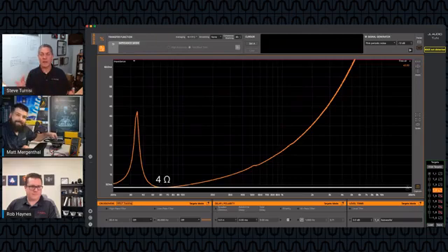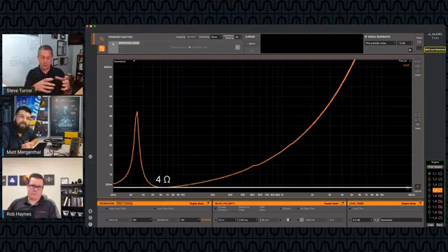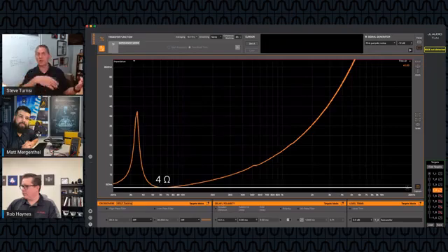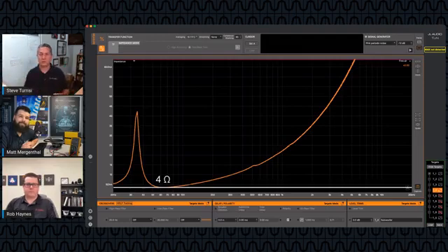So what's basically happening is when you're measuring the DC resistance of a speaker, there's a little bit of energy from the magnet that's affecting your measurement. And as you move the speaker, now you're creating additional voltage and current that's pushing back against your meter, and your meter has no idea what to do with it, which is why the values jump all over.